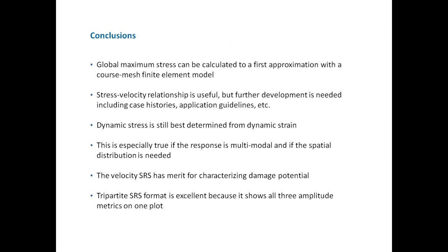Okay, just a couple of conclusions here. The global maximum stress can be calculated to first approximation with a coarse finite element model. We're going to do finite elements later on in an upcoming unit. Stress-velocity relationships are useful, but further development is needed, including case histories, application guidelines, etc., and even consideration for multiple modes.